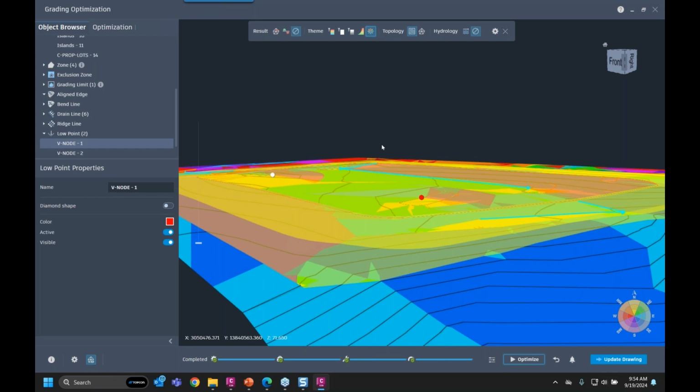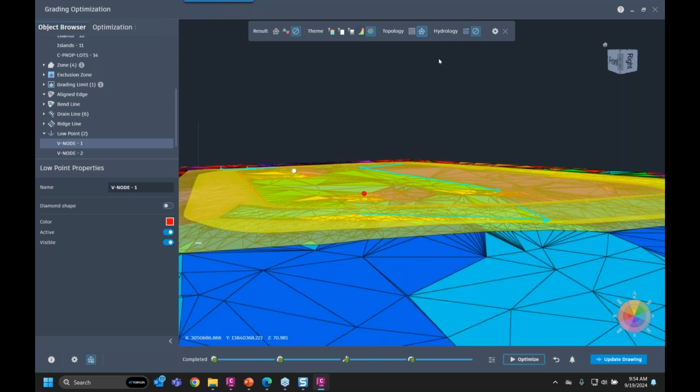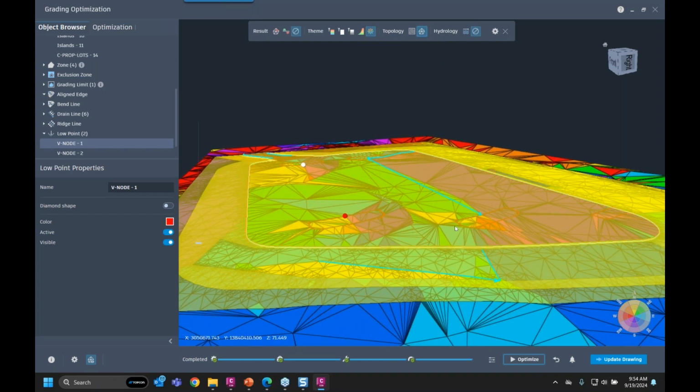I've noticed that in Civil 3D on its own, sometimes when you're using the object viewers, or if you don't have renders or analysis styles created, it can be hard to see because it's often the same color. So again, we can go into this and say, show me just all the TIN lines too. That's one of my favorites because I always want to know how things triangulate. Do I have to go in and add break lines?